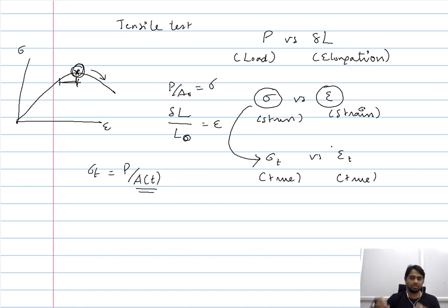So even though your machinery or the setup will render the results based on engineering stress and engineering strain, through some numerical operation, it is possible for us to convert the engineering stress and engineering strain to that of the true stress and true strain. So for all these reasons, the conventional or the most accepted representation of the tensile test results has been engineering stress and engineering strain.